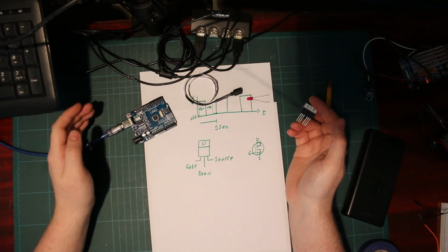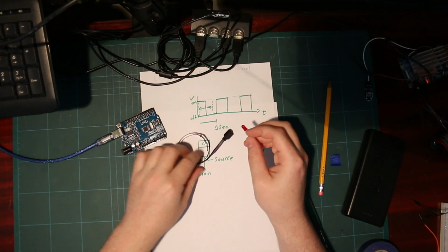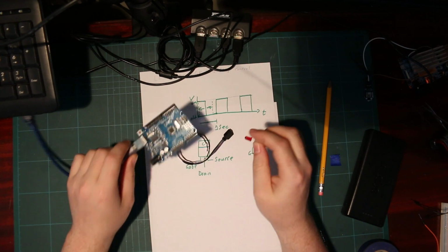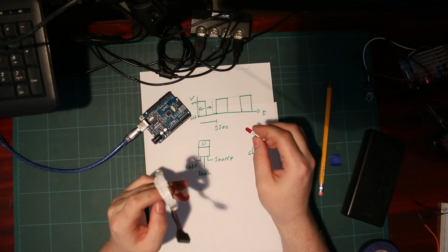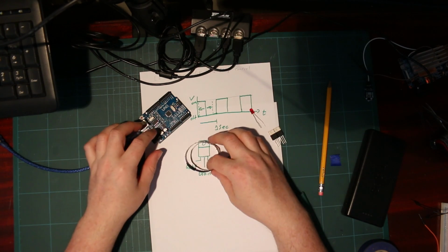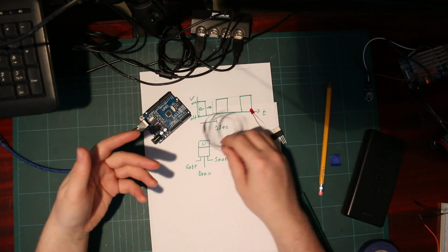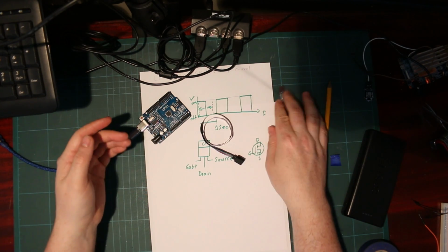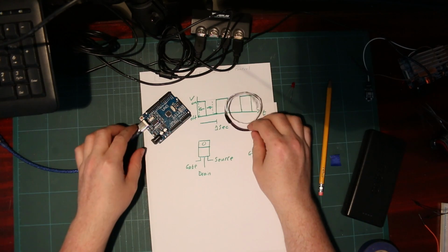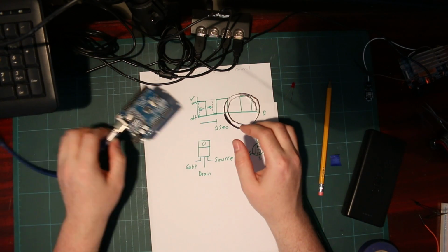As we've just said, the issue we have is that our standard Arduino can't output enough power to turn on a full LED strip. The reason being is, well, one, this requires 12 volts, and then also the power requirement on top of that 12 volts is going to be quite high depending on how many LED strips you have, and these little microcontrollers aren't built to handle that. You'll fry stuff in here.